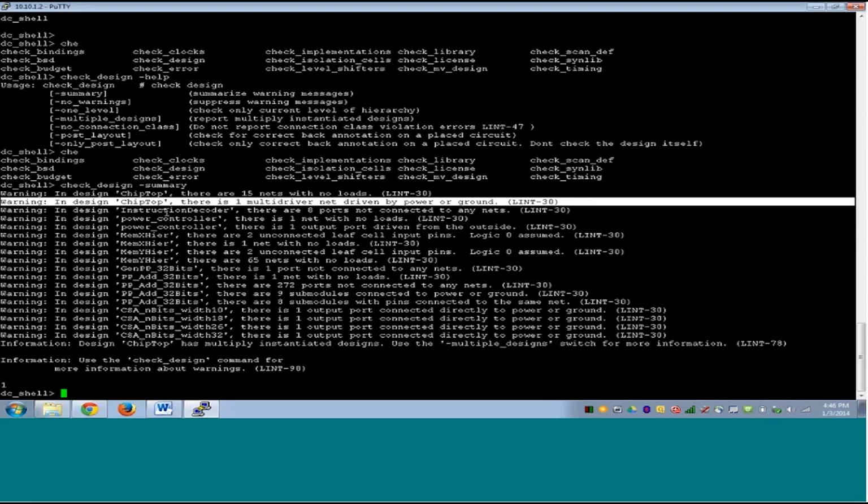Ideally, for cases like multiple drivers or tri-state drivers, you should instantiate the cells directly and explicitly. You should not let DC map any tri-state logic to a tri-state buffer. It's good practice not to have any tri-state logic as part of your RTL, because it complicates things later in timing analysis. If you want tri-state or a multiple driven signal, you should use it explicitly in your RTL, not let DC infer it.